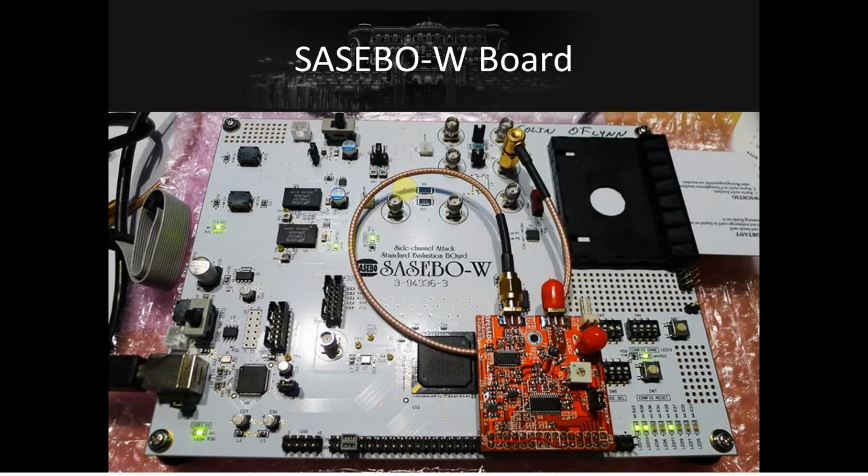So they have the reader and everything set up already. This OpenADC you can actually plug right on conveniently. It turns out it wasn't originally designed explicitly for this, but the OpenADC was designed to be flexible enough to work for applications like this. You can have this complete, nice looking transportable design. And the cool thing is this FPGA here is a huge one. If you know, it's a Spartan 6 LX150. So you can either store a lot of traces right on the FPGA, and you can even do processing on the FPGA if you really want to get into doing some of these attacks in real time.